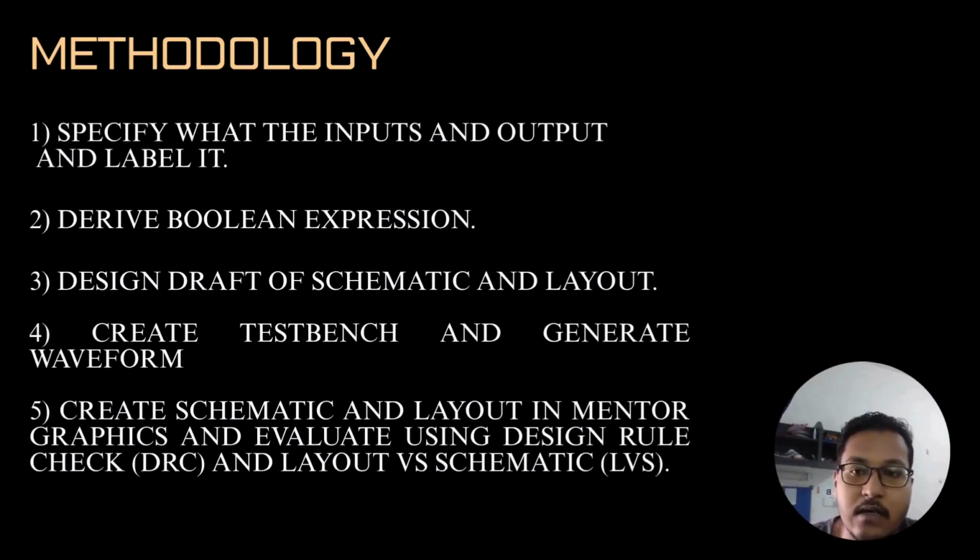After that, our methodology for our project is to specify the inputs and outputs we are going to use, then derive a Boolean equation, and then we draft our schematic and layout. After that, we create the test bench and generate a waveform for the schematic. Then we create a schematic and layout in Mentor Graphics software and evaluate the design using DRC rule check and also layout versus schematic.